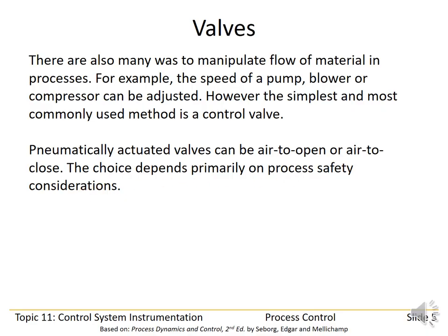In particular, we consider what we would want the valve to do in an emergency if the air pressure signal was lost, if there was a break or a leak in the air pressure line. In an emergency situation, would we want the valve to open or close? If we're talking about cooling water to a chemical reactor, in an emergency situation, we probably want the valve to open, and therefore we would choose an air to close valve.